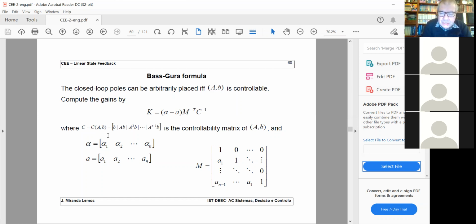Suppose that you do just an output feedback, okay? So you compare the velocity and you have a big error with a big gain. You have a big excitation to the motor. The excitation would mean that you are injecting a lot of fuel, but the fuel that you can inject has a maximum value. So due to this saturation, it's not possible.